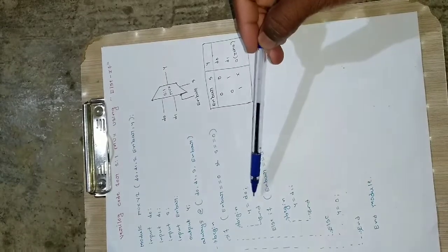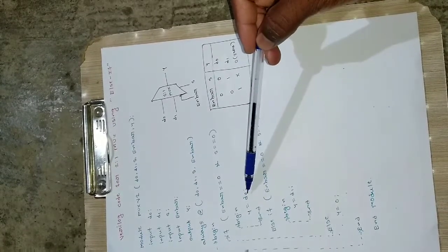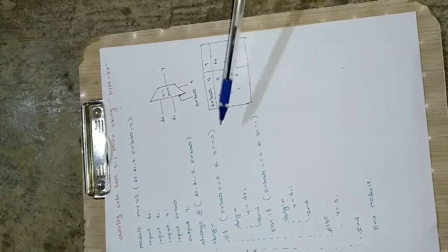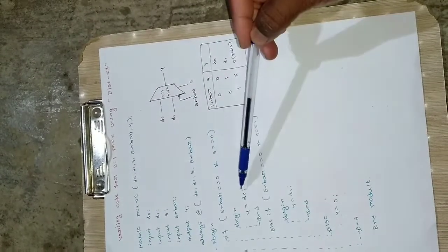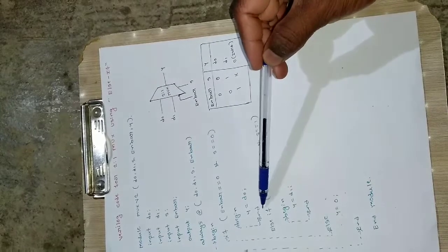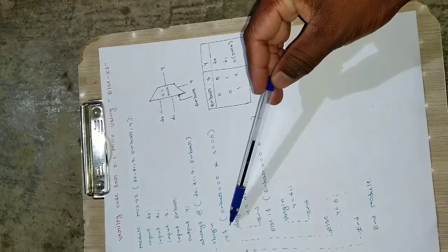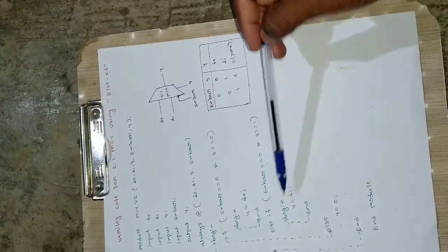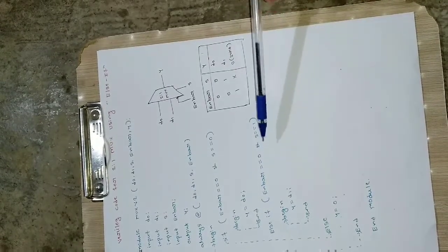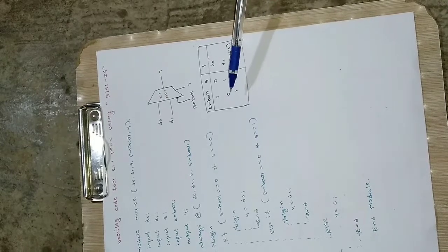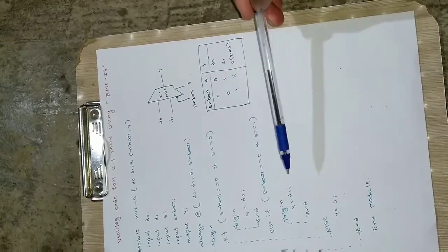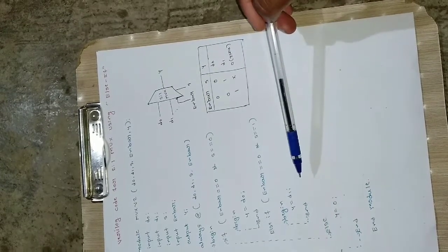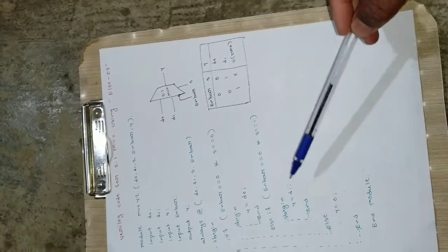So begin, assign Y equal to D0. So for the 0 0 condition the Y value is D0 here. Then for this begin there will be an end, and after if we will be having an else if. So else if enable bar value is equal to 0 and S value is equal to 1, that is the 0 and 1 condition, at that time for else if we will be having a begin, assign Y equal to D1, and end this begin.